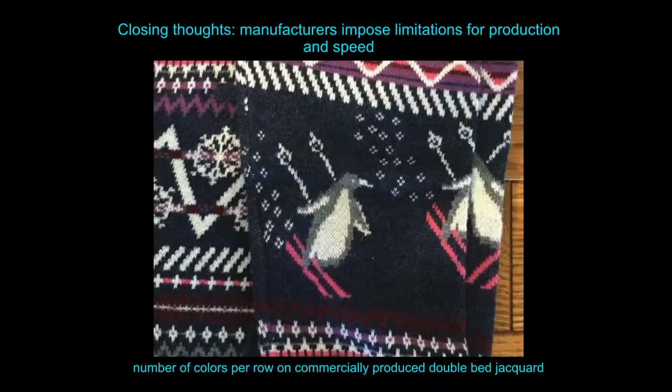The other thing that manufacturers do is that they limit things to a very specific type of yarn. So you see almost everything is in acrylic because it's very reproducible, and acrylic is actually very friendly in a knitting machine, and it's also cheap, and it's also abundant in the form that you need it for an industrial knitting machine. That means coned, properly tensioned on the cone, in big cones so you don't have to swap the cones as much.